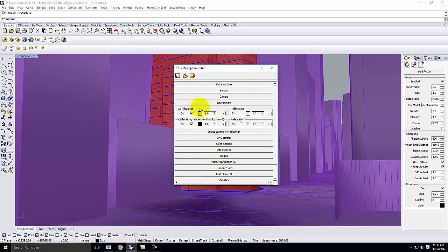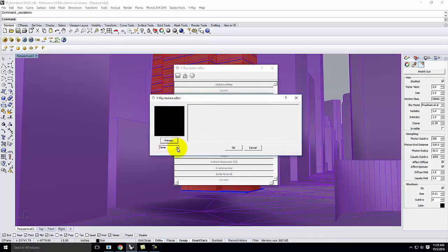And you've done this before, and you've changed the sky color before, maybe. I'm going to go ahead and instead of changing the sky color or the background color, click on this M right here, and I'm going to assign a sky. So this looks very familiar to our normal texture editor, but instead of picking a bitmap or anything like that, I'm going to scroll down, and I'm going to choose texsky. Once I choose texsky, under the default sky options here, I have sun. It says none. Well, that's not right.